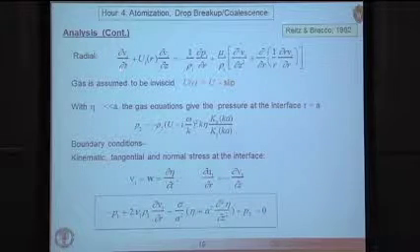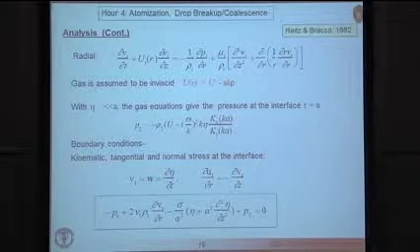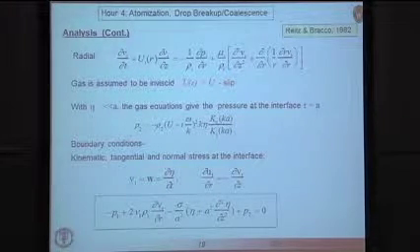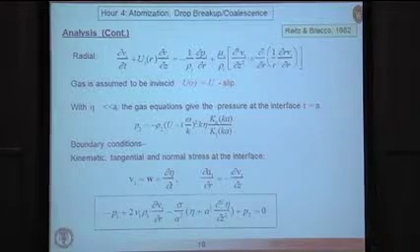So the radial component of the momentum equation is shown here again for the radial velocity component. Here's that U again. And typically, if the gas is assumed to be inviscid, which is actually not a bad assumption, then the boundary layer between the liquid interface and the gas can be neglected, and one can just replace the relative velocity with a constant, which is the injection velocity.